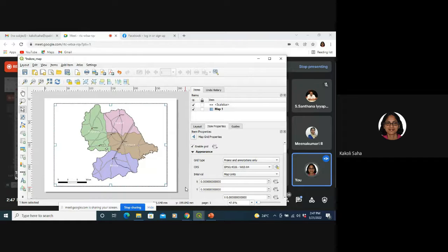You yourselves can try it. Like I changed the CRS, you can keep the map CRS. If you keep that, what happens in the UTM is that it will show several numbers, how many meters in the northing and easting. The UTM takes 0 for the equator, and the farther north and south you go from the equator, it will show that distance in meters. Sometimes, because we are not familiar seeing that, the meter coordinate is not very understandable to a commoner.